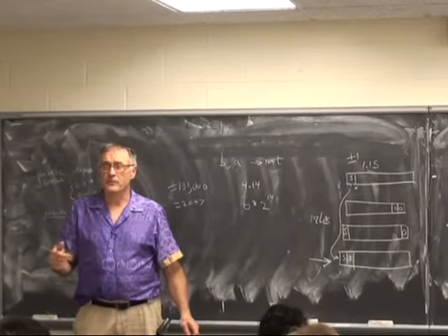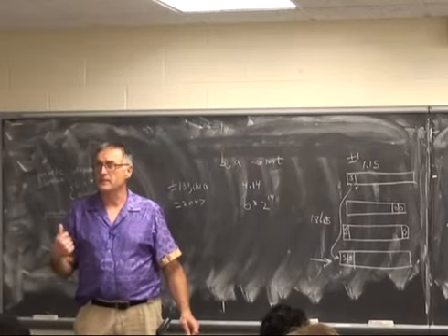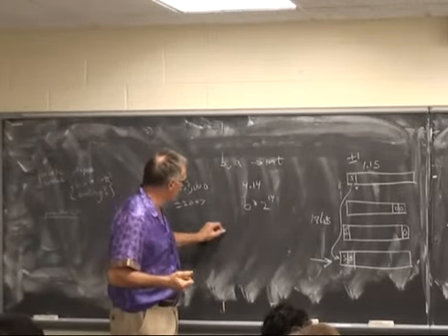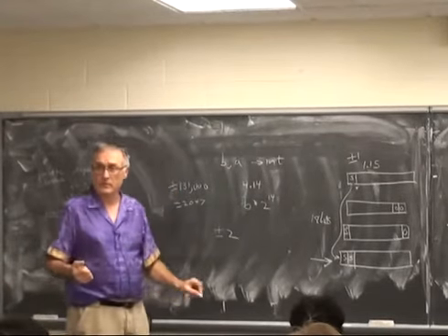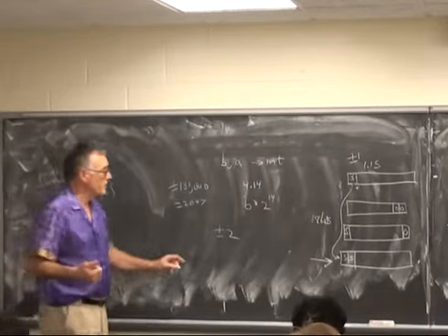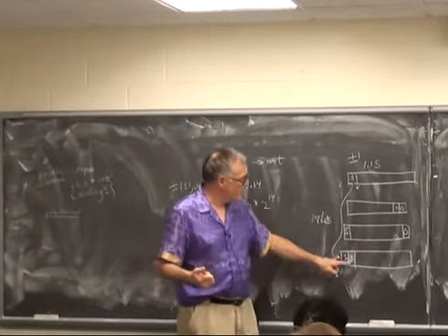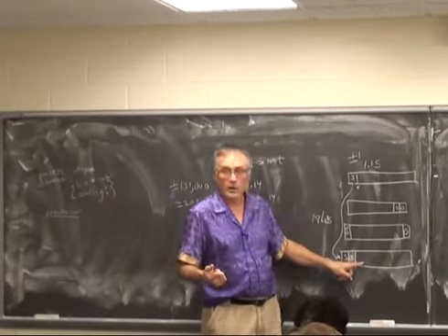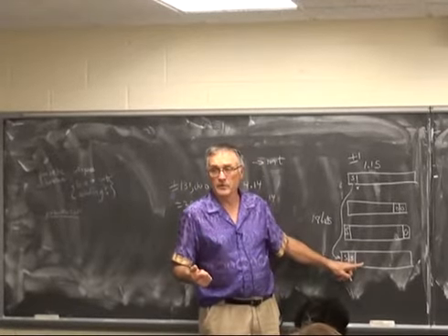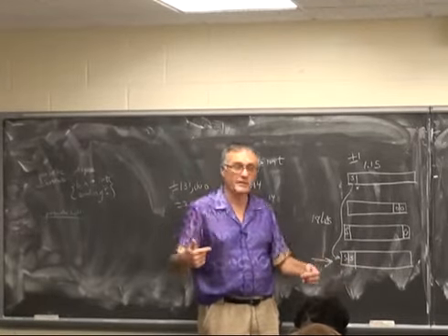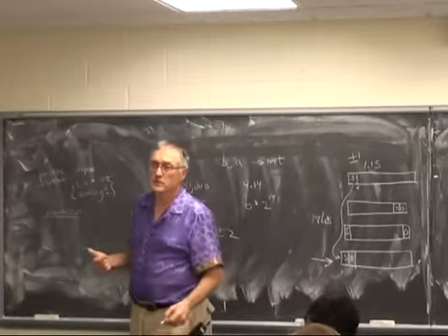I think for the particular filters I specified, the coefficients are all in the range of plus minus 2, less than or equal to the absolute value of 2. And so if you're shifting this fraction down by 4, then you should certainly avoid overflow. You're shifting 2 bits, you multiply by 2, you should still have a bit to spare. So that should help with overflow.